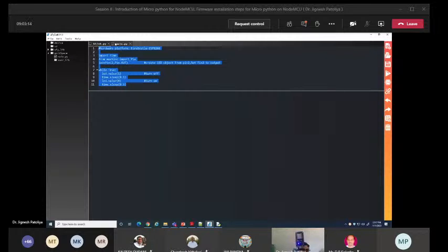So that's why, according to the default setting, if we want to store or run the application in our flash memory, then we have to prepare the file main.py instead of any other file.py.